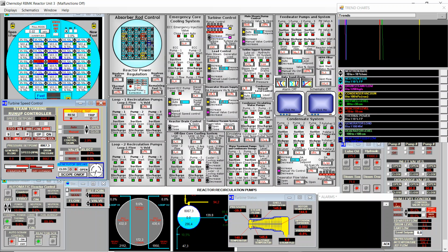But once we get to a very low discharge of steam, if we close a lot the valve, this temperature here, the entrance steam temperature, will also decrease, and then we'll start getting problems. So I will decrease a bit more to 1.9. Shell and rotor are still at very equal temperatures. But now we see the entrance temperature is very low, is 116, becoming lower and lower.